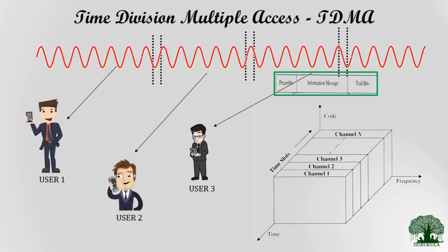So this kind of multiple access cannot be used for continuous transmission applications. If a user has to communicate continuously and with a larger bandwidth, TDMA will also fail. In order to address these problems, we should come up with a technology where there are no restrictions on the frequency band or the time, but still the users are separated so that they can access the spectrum simultaneously. Such a special multiple access technique is what we call code division multiple access.